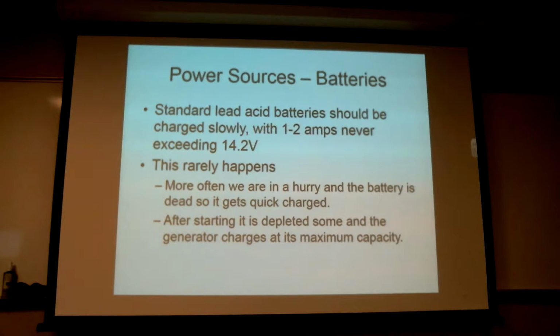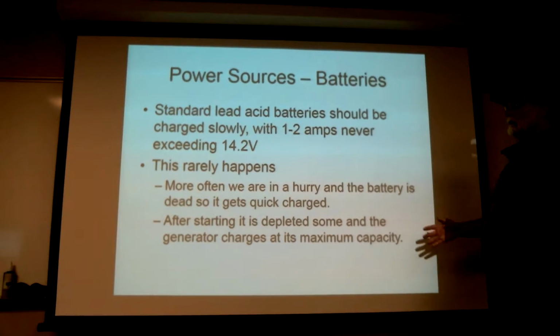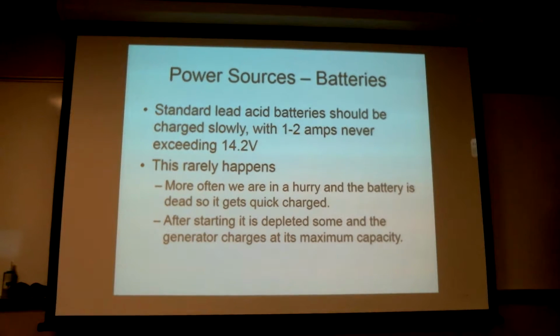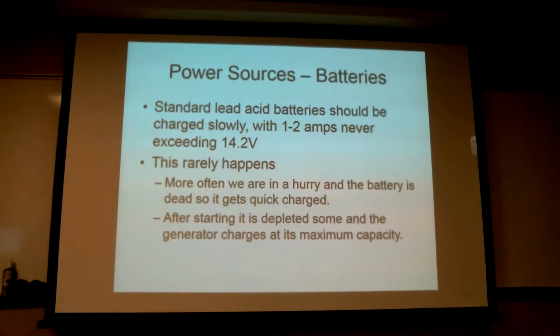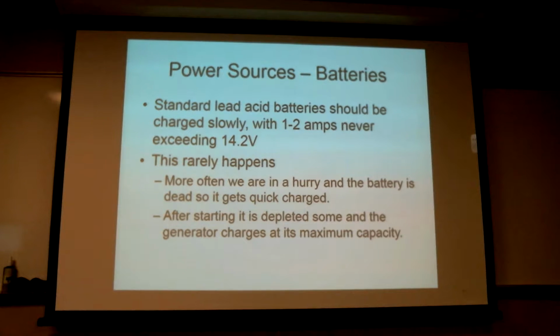On your car you don't really know, but in my airplane, when I go to start the engine, it typically hits about 28 to 30 amps for a few minutes, and then it comes back down to its normal 14 to 15 amps. So initially, to recharge the battery, at least the AGM, lead acid is going to be a little bit different, that battery will take 15 amps or so until it starts to get charged back up again. Now remember, the amount of current a battery will take is a function of the state of charge and the type of battery it is. Different types of battery have different internal resistances.